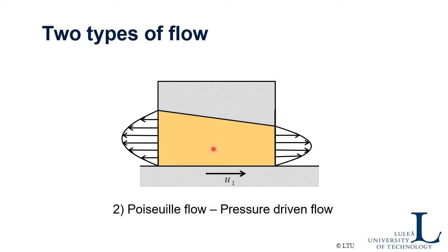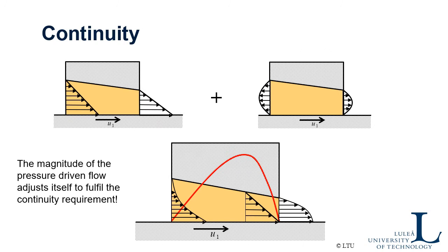So inside here we have a pressure, and that pressure will want, of course, to squeeze out or to force the lubricant out from the contact, and it forces it out in both directions, both towards the outlet and towards the inlet. And putting those two flows together explains how this flow balance or flow continuity can occur.